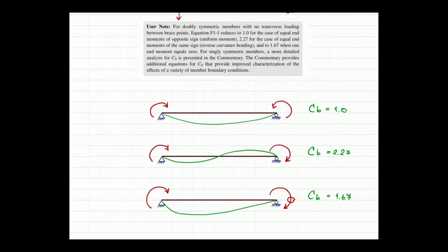Well, to be conservative, if you want to run the calculation on the back of the envelope, or you just want to do something where you cannot rely on workmanship, for example, if you design those elements used in deep excavation, you will not use a large value of Cb because you cannot trust the boundary condition. You are not so sure about the condition of the load, because the load might not be going in the same direction all the time in the real use of the structure.